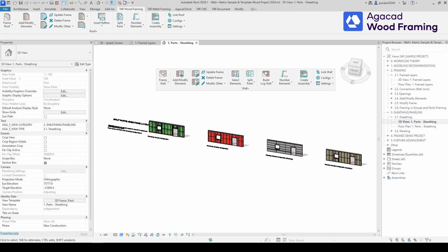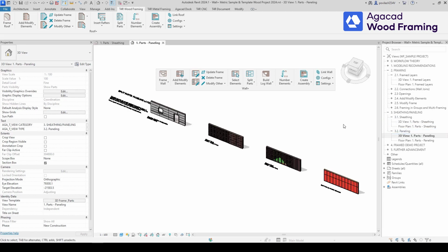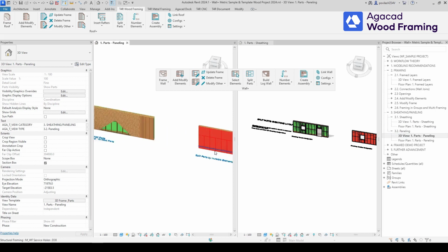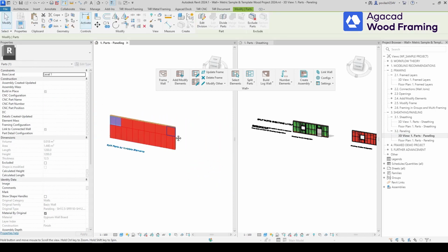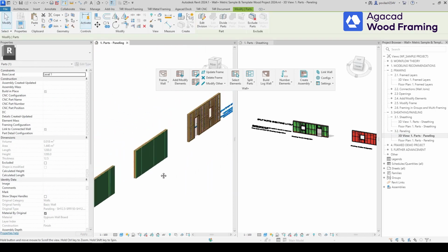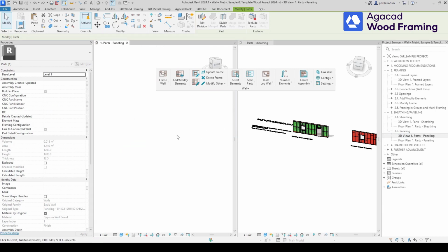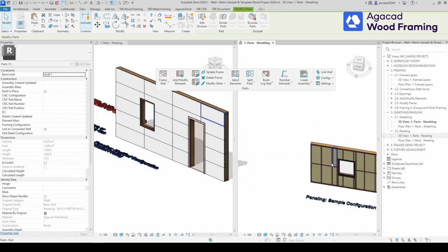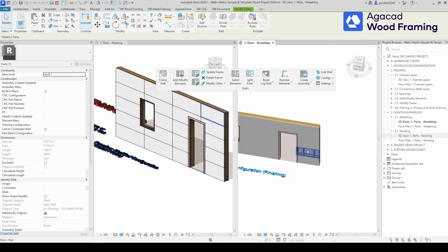So the other quite useful user interface upgrade is the hiding of unused tabs for sheeting and paneling. It's greatly appreciated by a lot of people so far, so I think it will be in the future as well. So it narrows down the configuration to exact sheeting you're editing, right? So I'm about to go into sheeting configuration and show you exactly that, right?